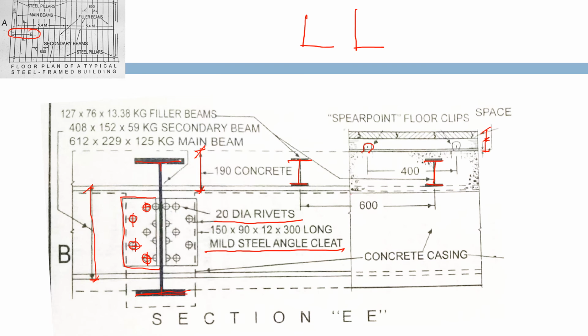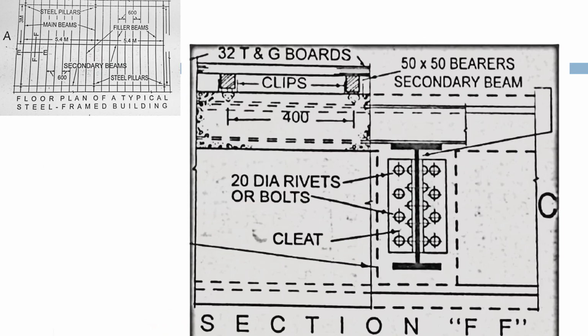Now this is the concrete casing which is done around the main beam to protect it from fires. You can see here, we have discussed this before during the stone chapter, that when you use an I section for a stone flooring also, you need a casing around it. So that is what has been done here also. We will see a view of this, but after another section.